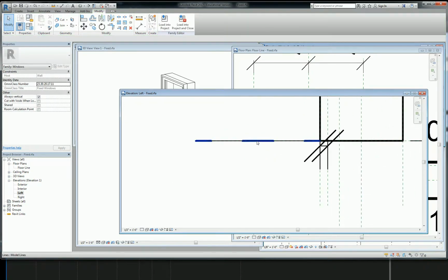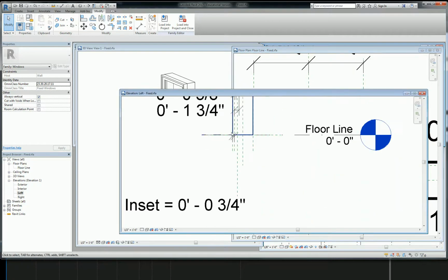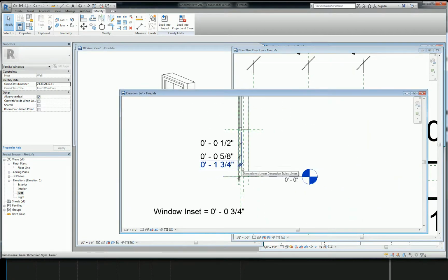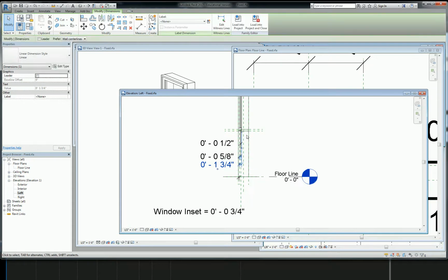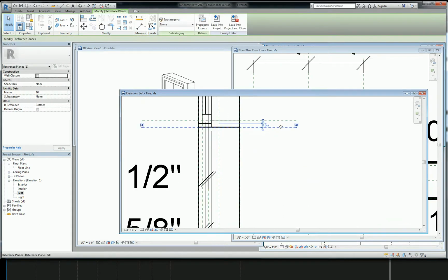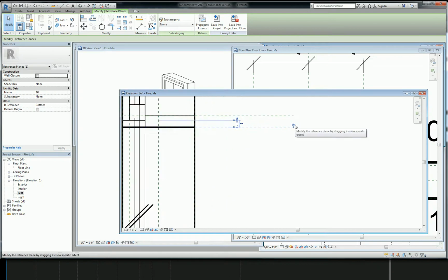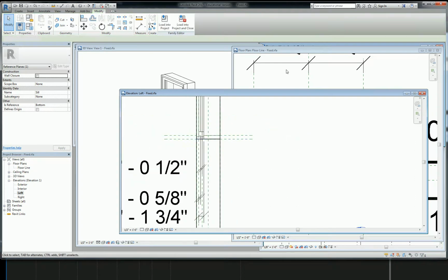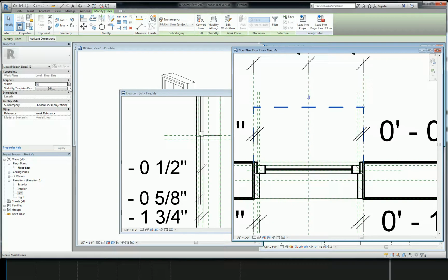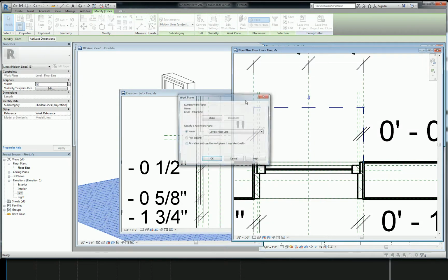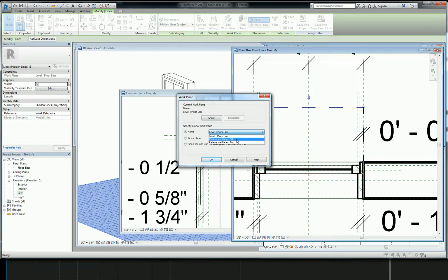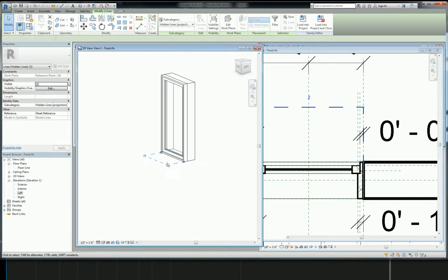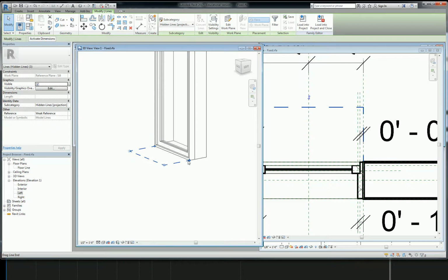All right, so they live right here, and I need to draw or basically associate them with a different reference plane. What I've got here, fortunately, is the sill, and that's probably a pretty logical place to put it, generally speaking. You can't really see the names that well up on screen, but it does say sill right there. So I'm going to take these 3 lines, and I'm going to change the work plane to sill. See that? Reference plane sill. Hit OK, and now it shows at the sill of my window.